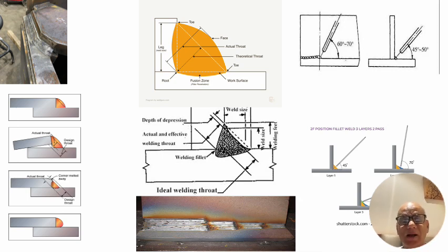Now, while doing that, like in the butt joint, we also have to check and ensure the setup. A good setup can give a possibility of very good weld. A bad setup can create a problem for us. We will not be able to measure the throat correctly, we will not be able to weld it correctly, and there will be an air gap which is going to remain here. And if it is a fillet with a lap kind of joint, there is a possibility of the corner, because of the arc voltage, getting melted down.